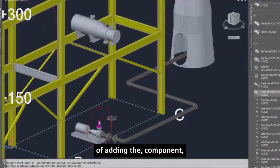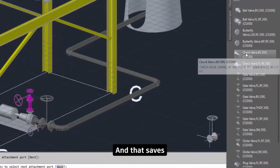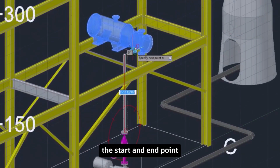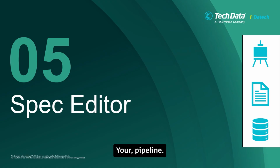Next, in terms of adding the component, you can just drag and drop the component from the tool palette, and that saves you most of your time. And you can just select the start and end point. AutoCAD Plant 3D takes care of the rest, a feature that helps you to auto route your pipeline.